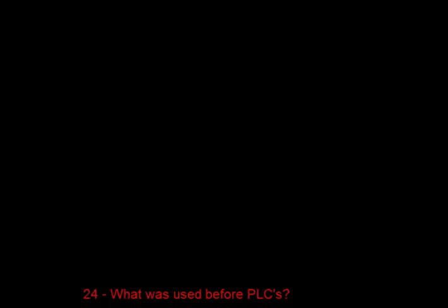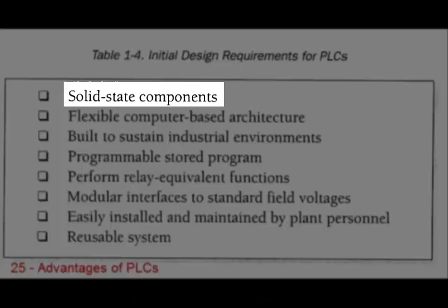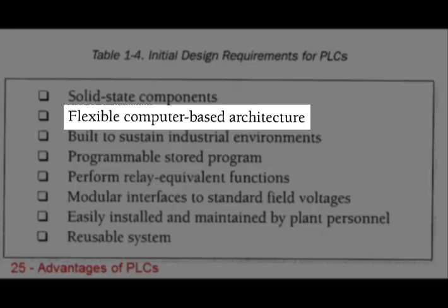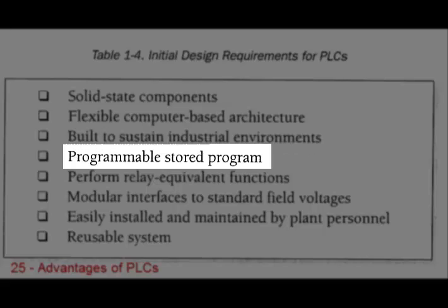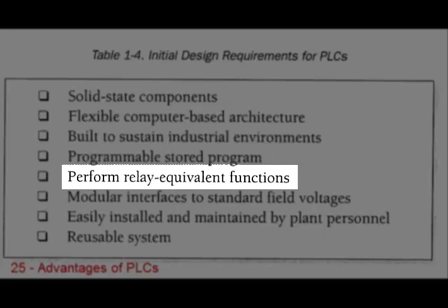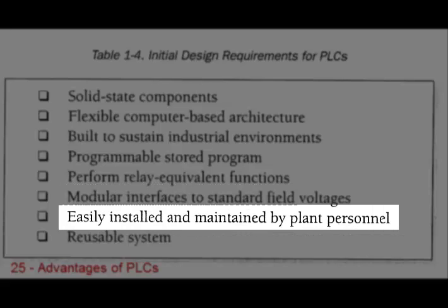What was used before PLCs? Relays. The advantages of PLCs include solid-state components, flexible computer-based architecture, built to sustain industrial environments, programmable stored program, perform relay equivalent functions, modular interfaces to standard field voltages, easily installed and maintained by plant personnel, and they're reusable.